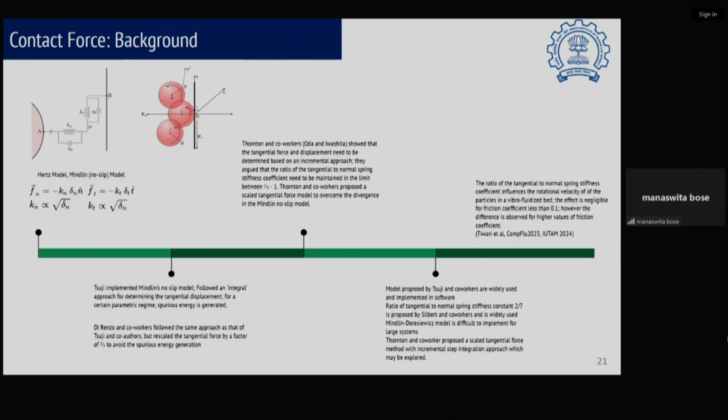If you are choosing a nonlinear spring, you have to be a little careful about what you are choosing. I would always say that if you're doing it for the first time, please start with 2 particles or 1 particle and a wall, see how they behave, set the parameters, and then go ahead with the large scale simulations.